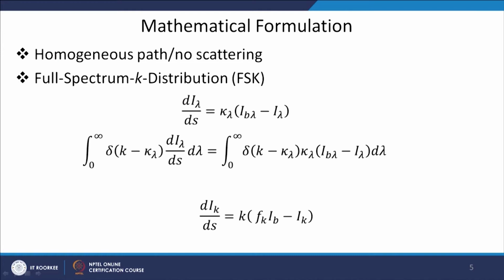So, let us look at the mathematical formulation of this method. This is our RTE. For a homogeneous path we will derive, but the method is not limited to homogeneous paths, it can be applied to non-homogeneous paths also. So, we will develop the mathematics of this method on a homogeneous path with no scattering. The method is called full spectrum because we will integrate over the entire spectrum. We will not limit ourselves to a narrow band or wide band, we will integrate over the entire